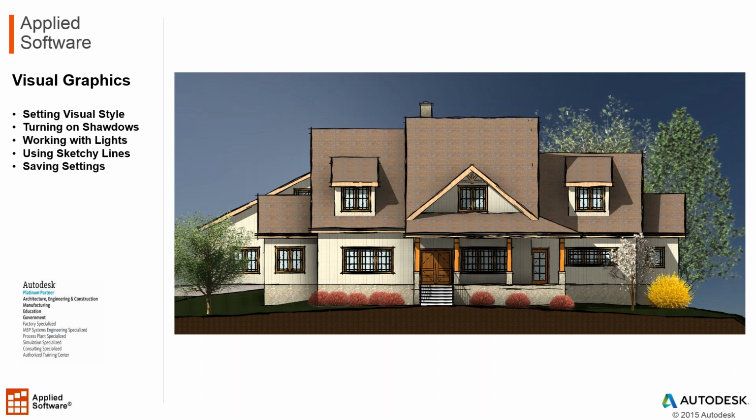So again, you can take any one of these levels of representation as far as what you'd like your elevations to look like. I just wanted to show you that all these are just settings inside the project that we can change and turn on. This is the same elevation. All I did was change the settings, and it graphically started changing the way it looked. And so you can set this up if you like this one as your default. We can tell it that this is our default way that we want our elevations to look.